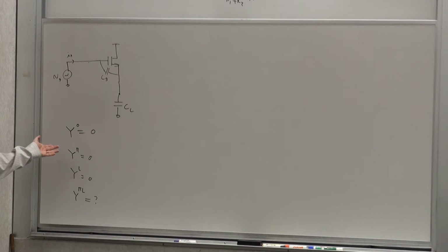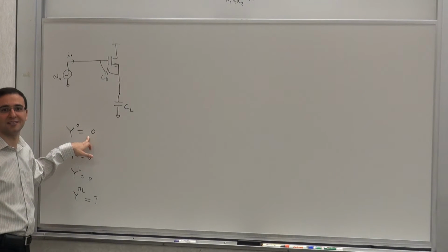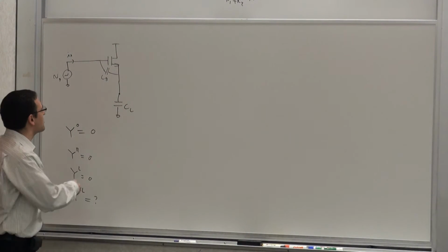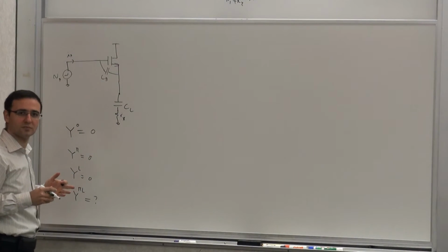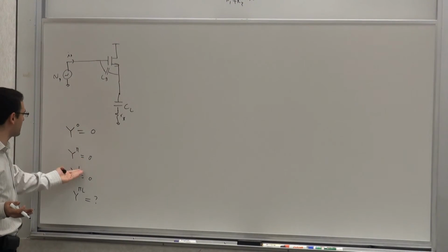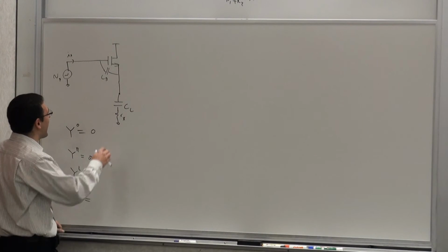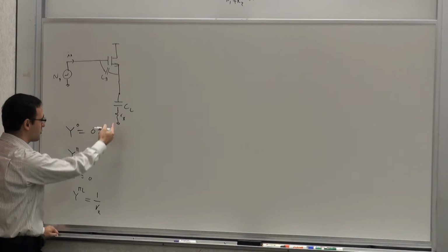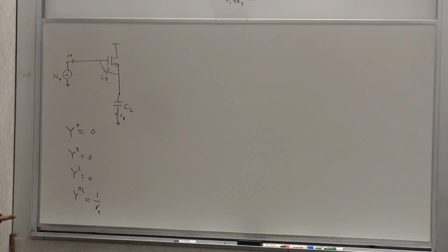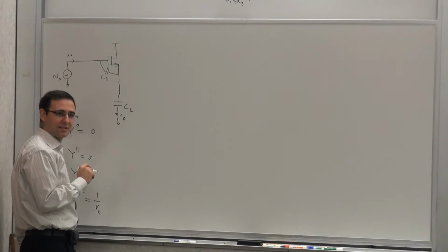You can apply current, but then you still have a similar problem, because then your Z0 will be infinite, right? Well, you can consider resistance instead. Yeah, just assume you put an arbitrary resistor there, let's say it's Rx, and redo the calculation with Rx. It turns out none of these three change, because they're still 0. They're open, it doesn't matter what resistance you have here. But now instead of this being infinity, when both of them are shorted, Y is 1 over Rx. And of course, as Rx goes to 0, it becomes infinity. But let's keep it in terms of Rx, and then we'll set Rx to 0 at the end. And if you have a problem there, then you have a serious problem. But let's see if you do.